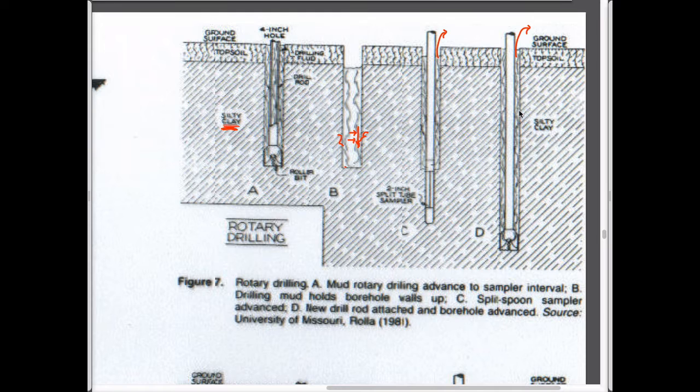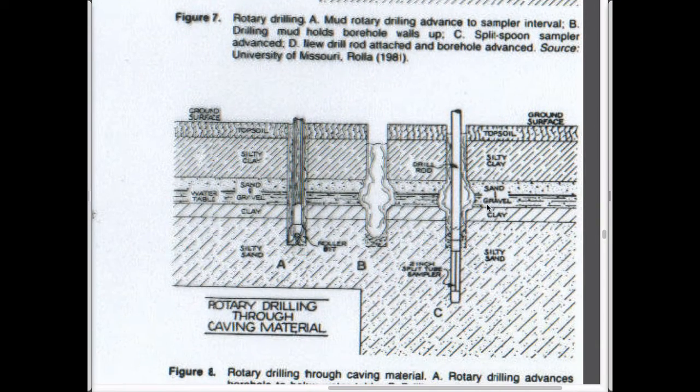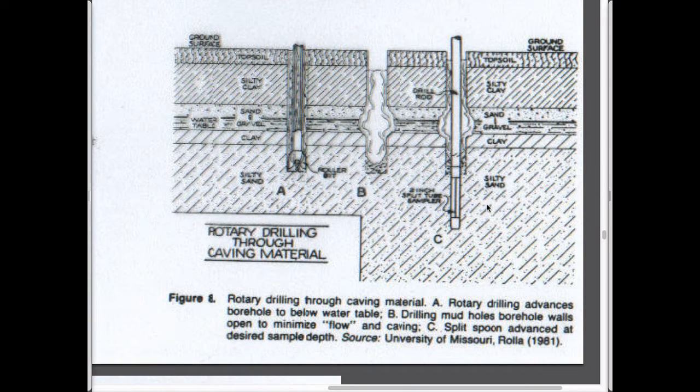What you do have the option to do, once you pull the drill string, is run a borehole camera down and look at whatever's there. So I guess this is making the same case as before. If for some reason your hole collapses, then you end up with this stuff at the bottom and you end up with this sample. The top of your sample is no longer pristine and you're not sure whether there really is a stratigraphic discontinuity at this place that you should know about, or is it just the muck that came down from here that washed into that?